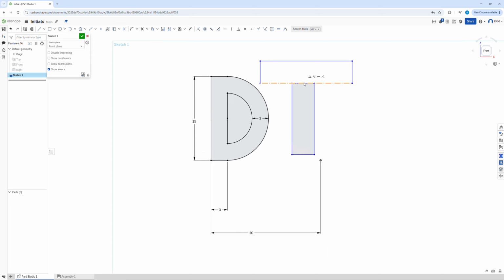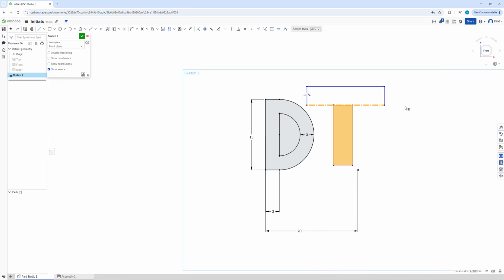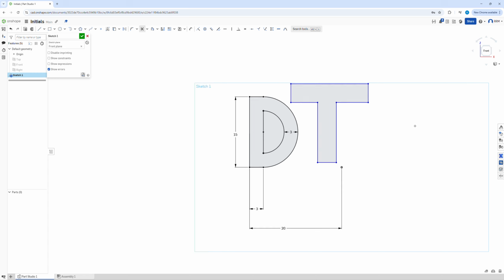as you can see. And I could also make this line underneath the construction line, and then we could draw back over it. But for the sake of this tutorial, we're just going to trim it with the trim tool. So I click on trim, I click once, I drag down and through, and both of those lines have now deleted themselves. In terms of dimensions, let's make this dimension here 3 millimeters, so it's all uniform. And let's say that it's going to have a height up to here of 12 millimeters. So we're going to make this one 12 millimeters.